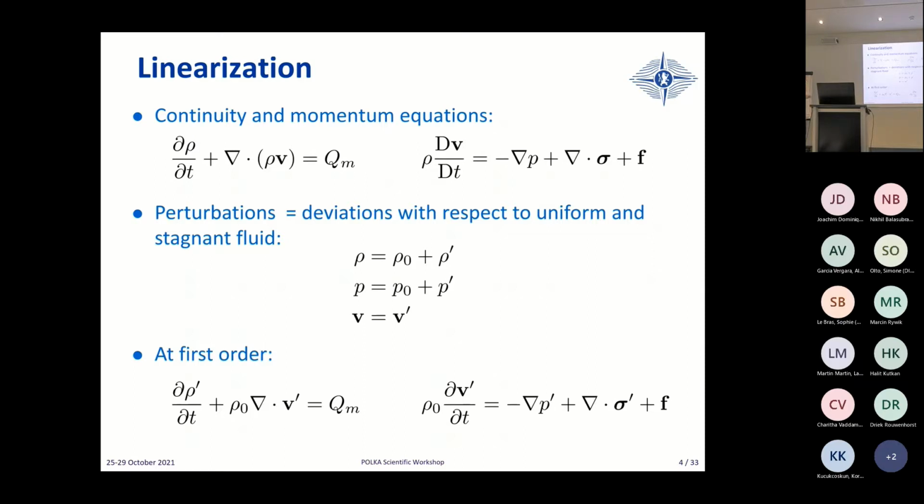Adrien will include the possibility for the acoustic waves to be carried away by the flow and all the associated effects in terms of acoustic refraction and convection. In this framework, we describe acoustic propagation like in this class: there's no mean flow, there are negligible temperature gradients, so it simplifies the acoustic propagation.